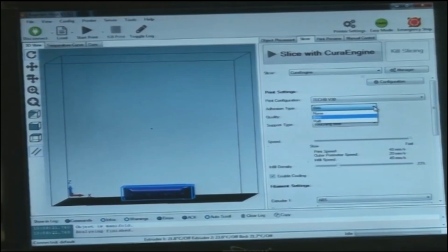About brim: what is a brim? As I said, it is just at the outskirts of the job. Brims are often used to hold down the edges of your part, which can prevent warping, and it also helps in adhesion with the bed.